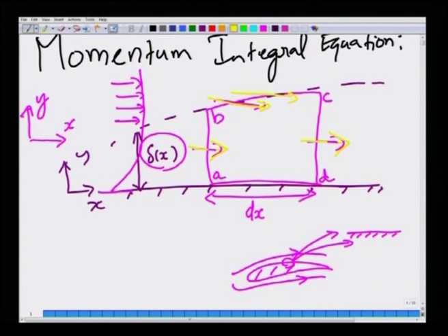So, fluid can enter the boundary layer through the surface BC also. We had derived the mass conservation equation for this control volume in the last lecture and related the various mass fluxes, and so the momentum can enter through all the three faces. Along the face AD, the bottom surface, it is a rigid surface, so fluid cannot come in through the face AD because of the no penetration boundary condition at the surface AD.